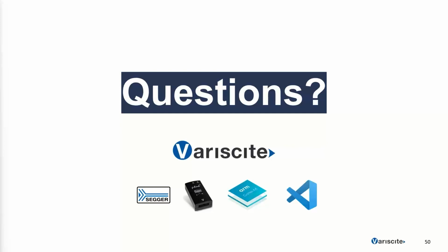Is there shared memory between the Cortex-M and Linux? The communication is all done through this remote messaging framework. The shared memory, I think, would have to be configured within the Linux driver. There are Linux driver examples for the two remote processor communication examples. So inside the FreeRTOS Variscite repository, there are the multi-core examples. There are several examples in that directory, and there are drivers aligned to those examples inside the Linux kernel. And so the Linux driver would be responsible for managing that shared memory.